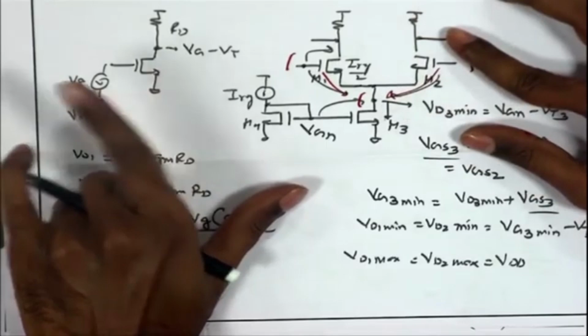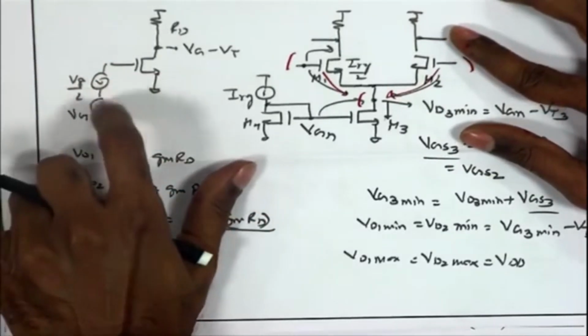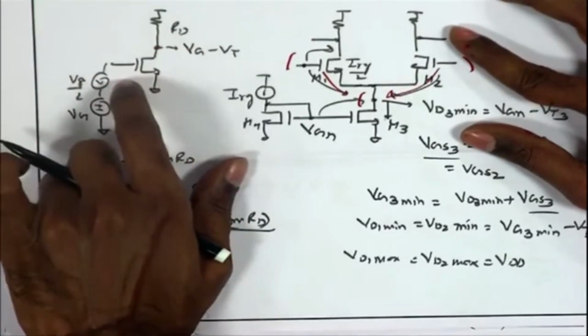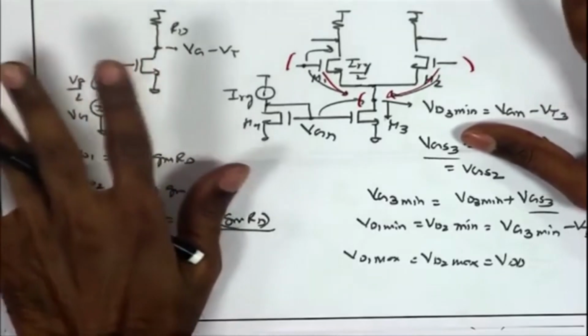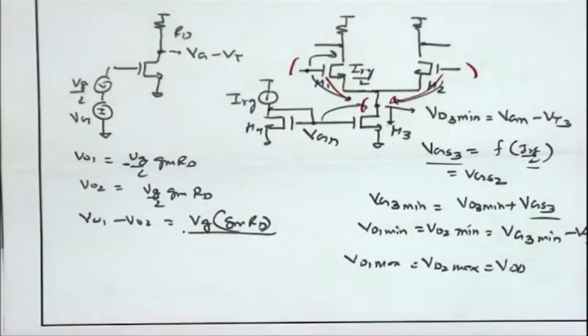Frequency response is going to be more or less similar to what we discussed in the common source case. In case you have a source resistance over here, the same thing, you can apply the Miller effect and break down the capacitances. So, exactly the same expression that we obtained for the common source. No need to discuss it further for the time being.